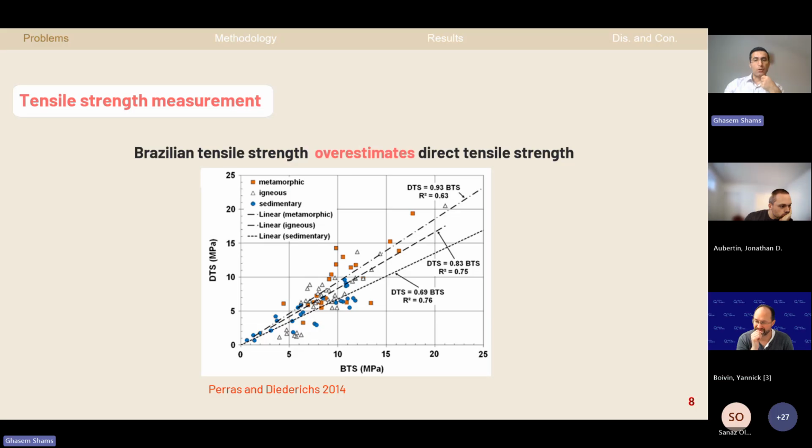Yes, coefficient of variation. We had a very small coefficient of variation, with very good consistency in the results, because we paid very close attention to sample preparation: the curing time, the testing time, the duration of testing, the loading, and all the sample surfaces, to decrease the uncertainties as much as possible. That's why we had a very small coefficient of variation, and we did more than 100 tests and samples.